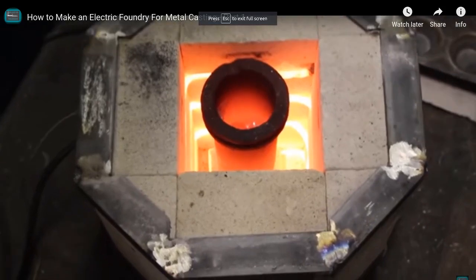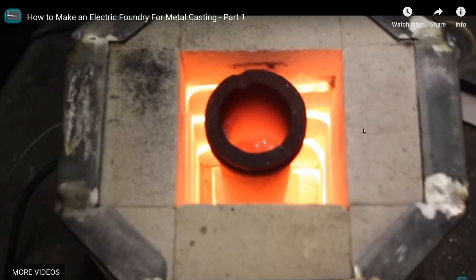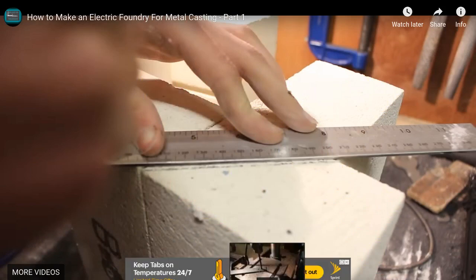Hey guys, today I'm going to be showing you how to use nichrome wire to make furnaces for heating and melting aluminum. You can't do steel, but you can do iron, like ductile iron or cast iron. That's doable, but in that case you would have to use Kanthal wire. So here's an example of a video where you have a ready-made homemade design using fire brick.